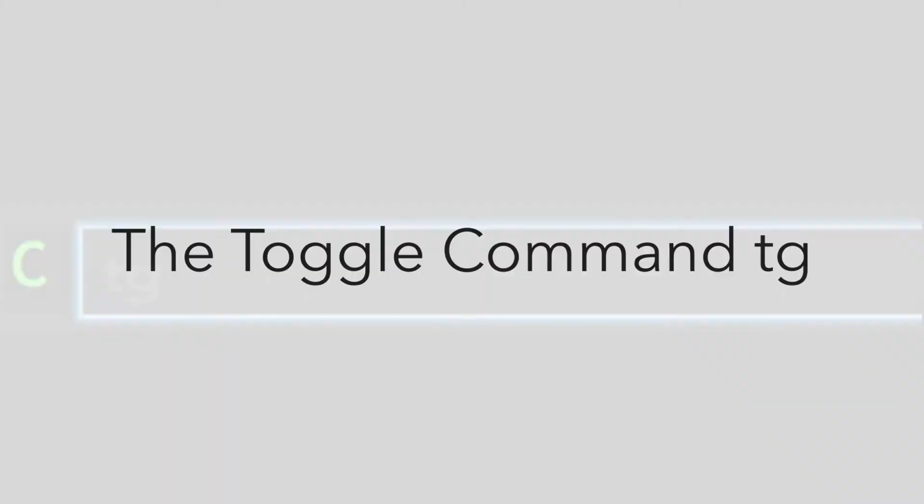The toggle command. The toggle command allows you to flip the current state of a port pin. So if the pin is currently 1 and you run the toggle command on it, it will become 0 and vice versa. The toggle command is called TG, which stands for toggle, and its argument is the name of the port pin that you want to toggle.